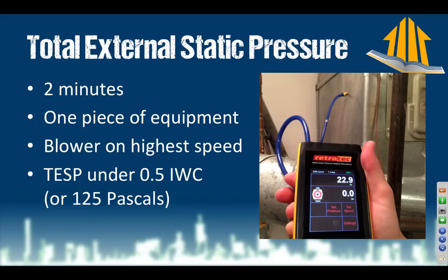I guarantee you that once you start testing this, you will find that 100% of the systems that you test are over that maximum limit. And that is because the person who installed this system did not test it, so they have no proof that they did a good job, and therefore the marketing that says, we do a good job, without any data is total BS. You cannot believe it unless there's actual data. You can also just use this in pascals, and 25 pascals is a tenth of an inch water column. So that's a pretty good reading right there.